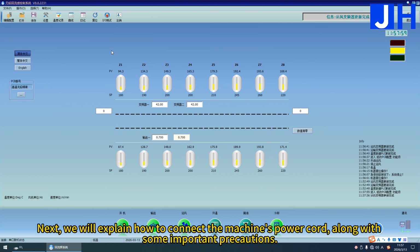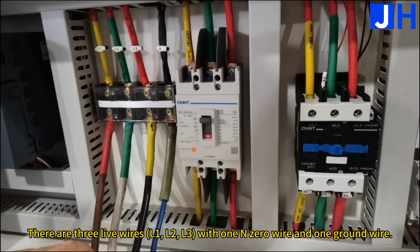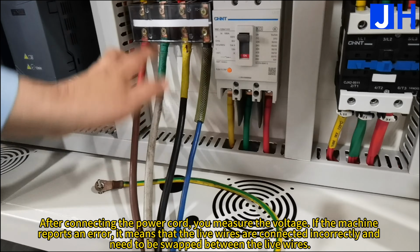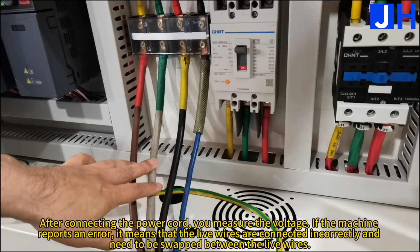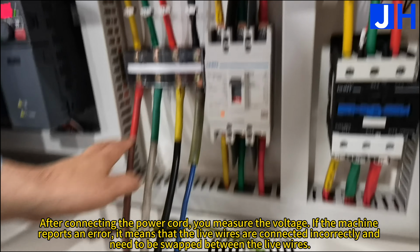Next, we'll explain how to connect the machine's power cord, along with some important precautions. There are 3 live wires L1, L2, L3, with 1 zero wire and 1 ground wire. The live wire is 380 volts. After connecting the power cord, you measure the voltage. If the machine reports an error, it means that the live wires are connected incorrectly and need to be swapped